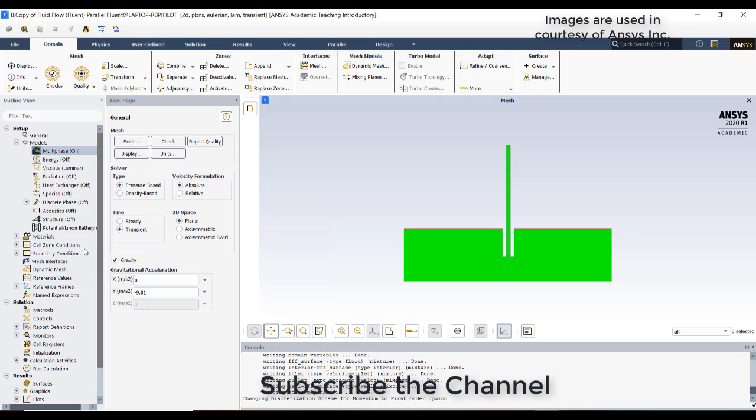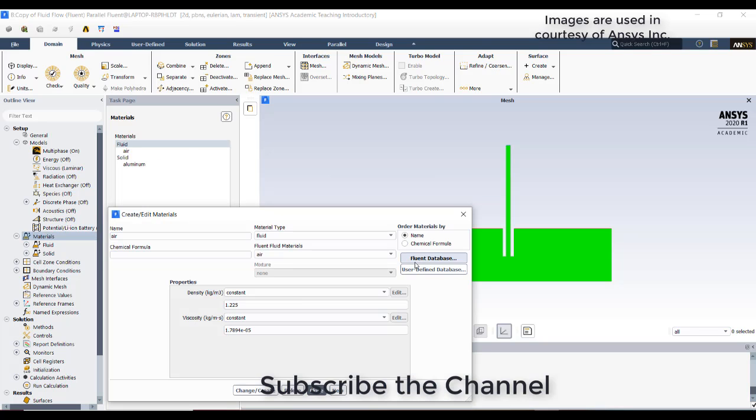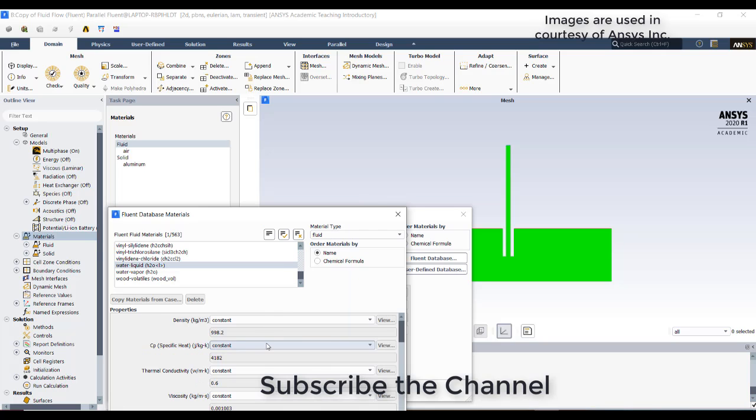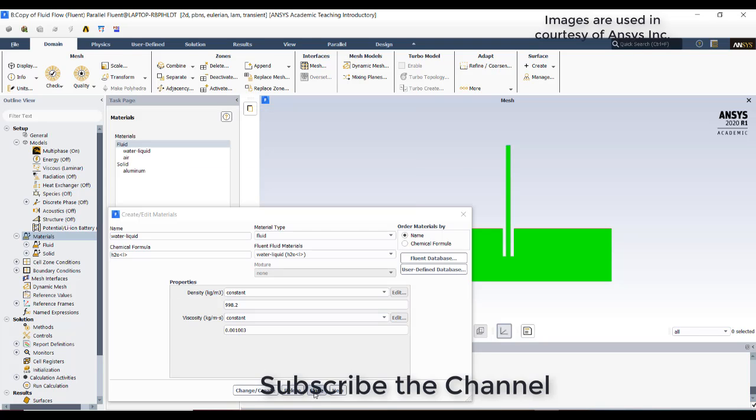Close it, go to the materials tab, and try to import water liquid from the Fluent database. Drag and drop, go to water liquid, copy, close, close.